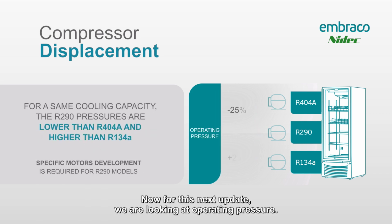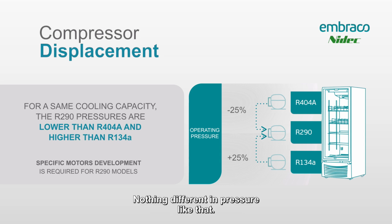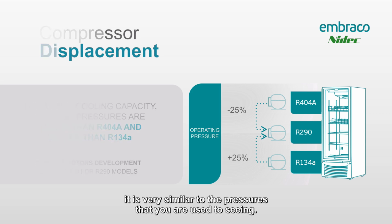Now for this next update, we're looking at operating pressure. And you can see again, R290 is right in between R404 and R134. This change is not like when HVAC systems changed over to R410. Nothing different in pressure like that. It's very similar to the pressures that you're used to seeing.